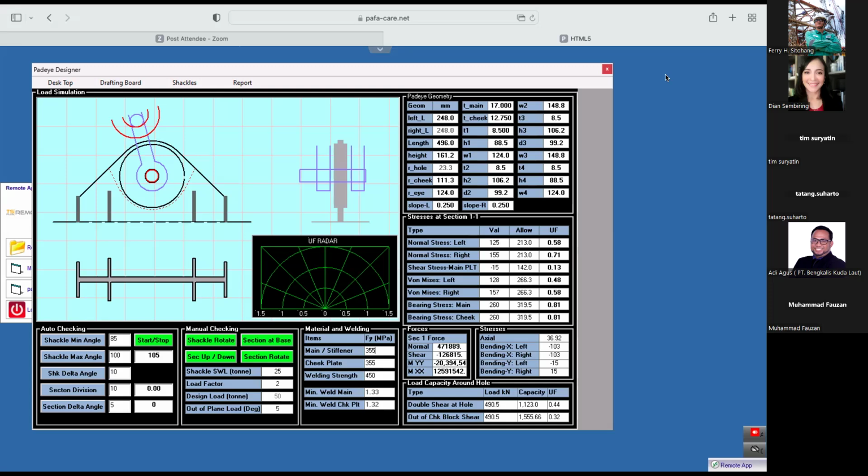Okay, thank you very much for the question. Good question. Basically, if you have designed the main weld between the main plate and the object to be strong enough, then you don't need the weld from the bracket or the stiffener to the main plate to carry the load, because the bracket is just to resist the lateral force.